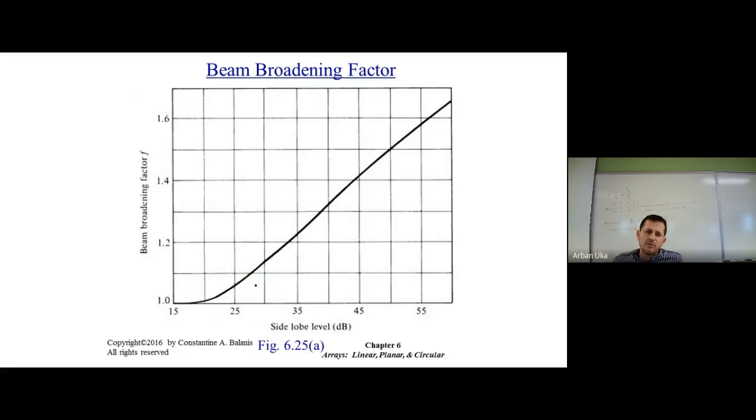In principle, this would mean that we can have a very strong signal sent at a specific angle, but we do not want to disturb receivers using power which can be radiated using the minor lobes, okay? So it's an important factor because we want to keep the antenna shut down at a specific angle range, but keep it on at a specific direction that we select to radiate to.